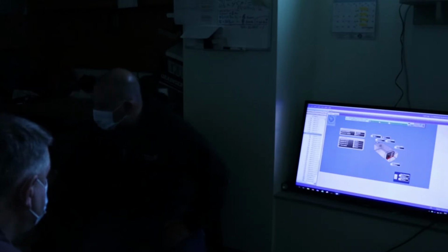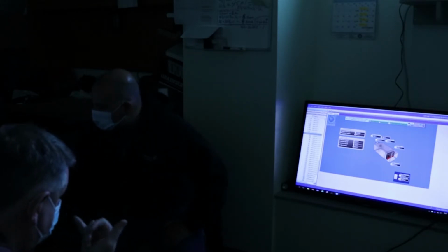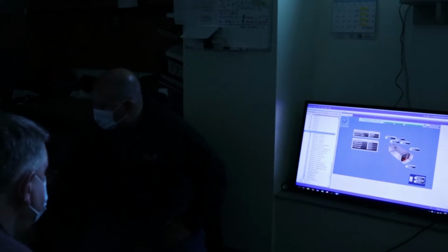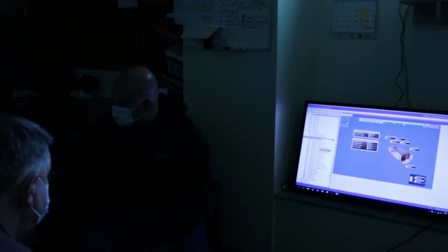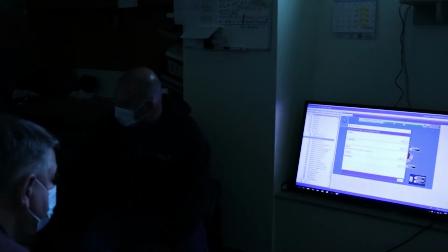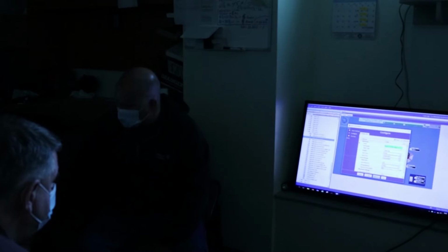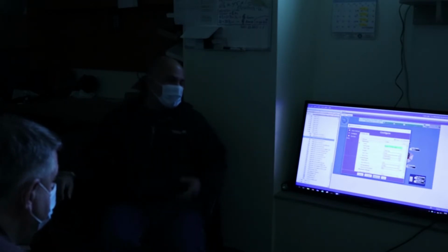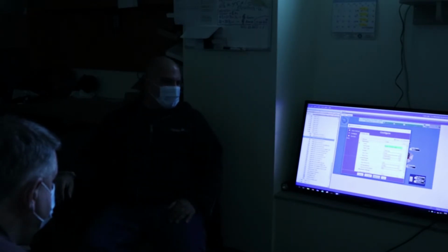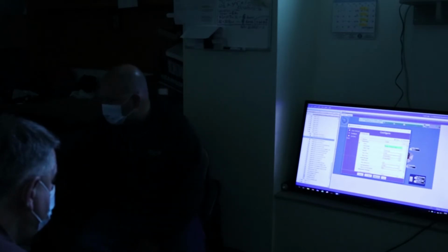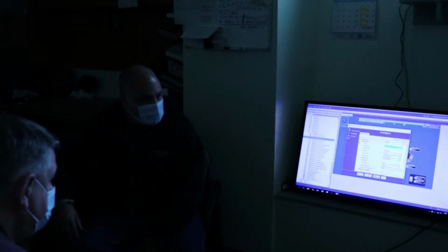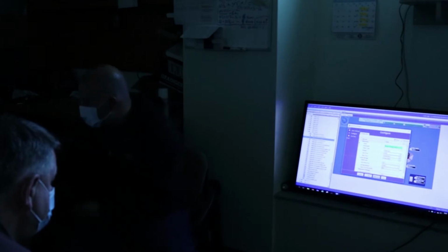So now, here's the zone temperature. If I right click on that and show extensions, I can click on that and it lets me add a trend. Okay? So with the trend, we're going to trend the zone temperature. We could determine how often we want to do the trend. I typically set them up for every 5 minutes. No, it's like 30 minutes. 30 minutes? Yeah, I think so.